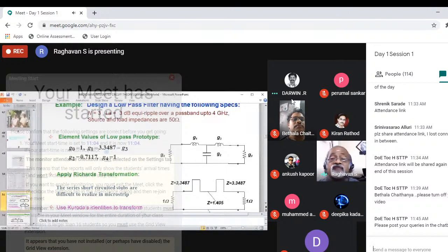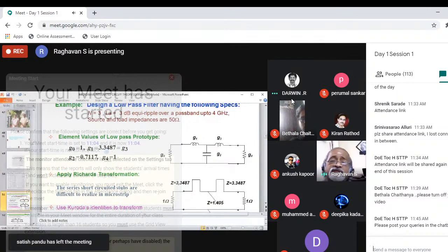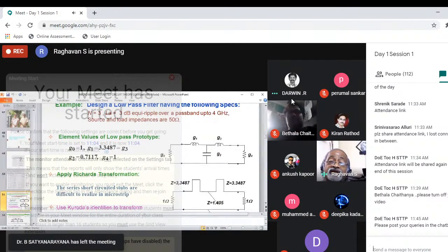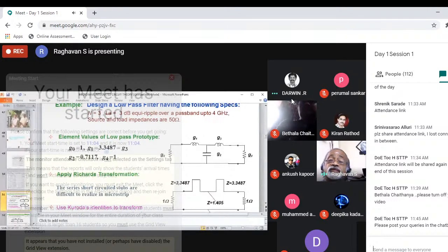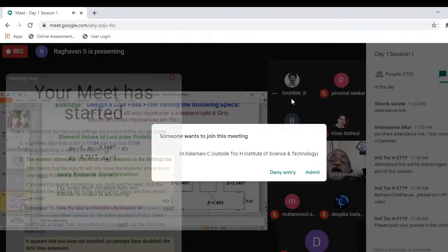First, in the filter form, you get the order. Only from the order specifications and the insertion loss, you can easily get the order. This is a simple three-section filter. You get the G values, either in Chebyshev or Butterworth or Bessel function, whatever the function may be. Get the G values, draw the lumped one, then get the equivalent distributed one, the inductor